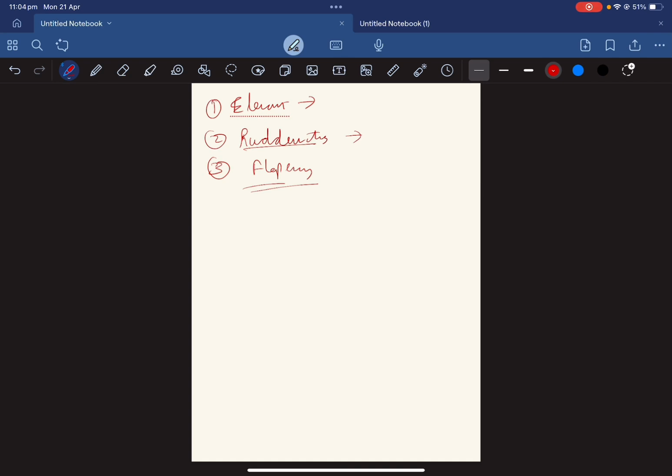And let's move to the other part, which is called trimming. This is important because you're going to use it a lot when you fly an aircraft, especially any type of aircraft you fly. It's going to be very common. So what does trimming do? Let's say you're flying, right, and to maintain straight and level flight, you have to hold the control column all the time at an angle so that it flies straight and level. So what if I do something so that without holding it, I get the same result as if I'm holding it, right? That would reduce my workload, and that is something I would desire.